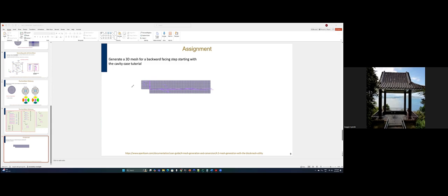That means anything that is flowing in this direction is not going to get here because this is now solid. So it's not going to be able to penetrate. So you want to make sure that these two are linked together, or these two are linked together, depending on the approach you decide on. The way to do this is to use the merge patch pairs.